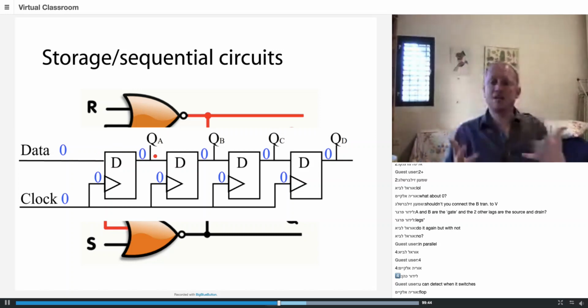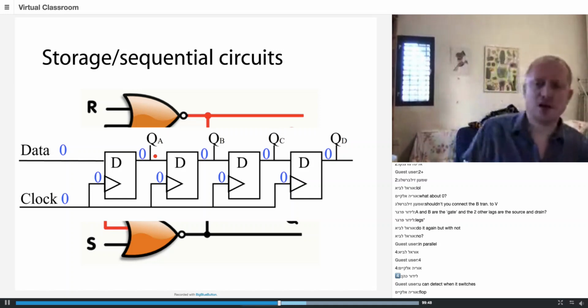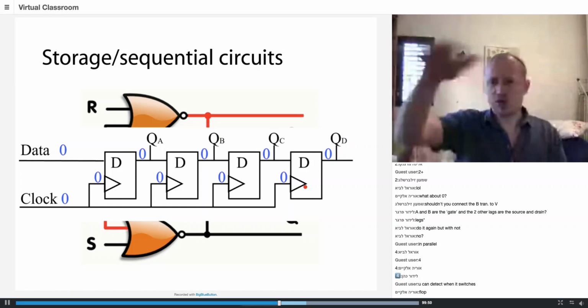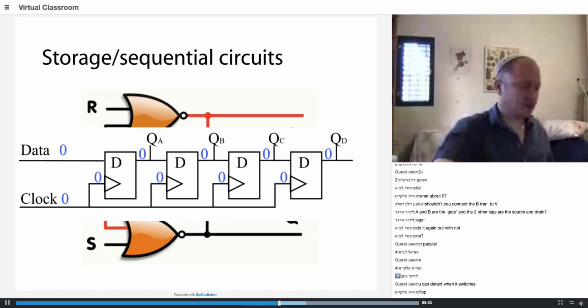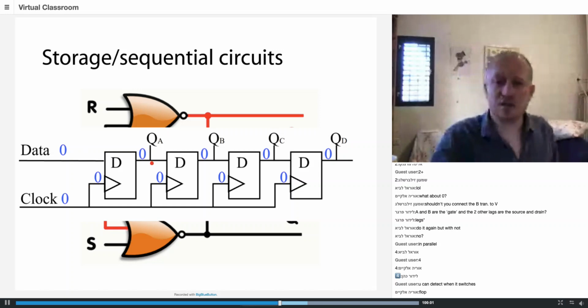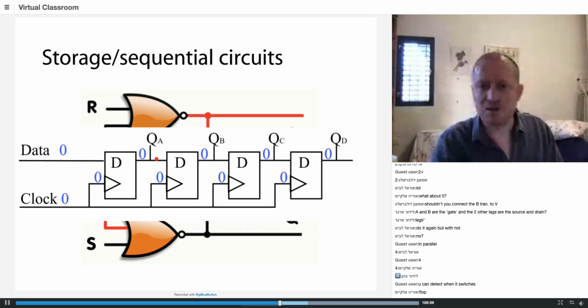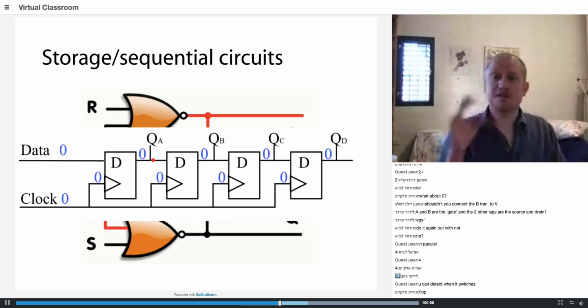And it's very, very useful to build logic devices this way, because you have a clock which is shared between all the devices in the system. This is 5 MHz, 2 megahertz, 3 gigahertz, and so on. And every once in a while, you bang this big gong, and all of the data goes out to the next step. Of course, between D and Q, between this step and the next step, it doesn't have to be a direct connection.